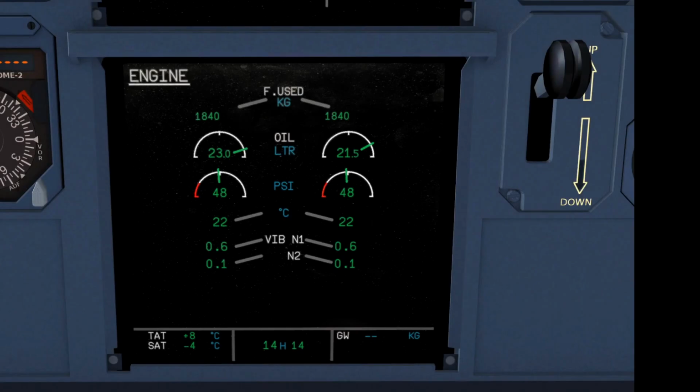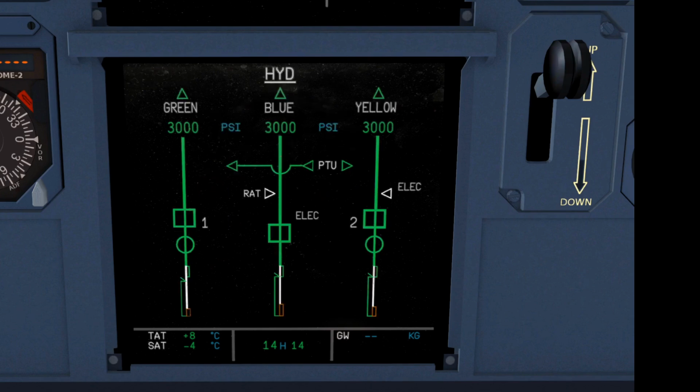This is a better viewing angle. Let's use a push button to view the information on the hydraulic system on this display. As you can see, this aircraft has 3 hydraulic systems identified. The hydraulic lines are shown in green, indicating that the systems are operating normally. The systems are labeled as green, blue, and yellow. Below their names, we see that the pressure in each system is 3,000 pounds per square inch (psi).